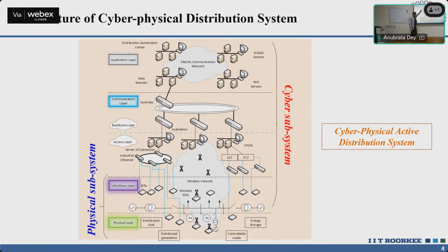And after that, the last layer comes, that is the application layer, where all your systems, let's say SCADA, then you have the advanced demand management side systems or energy management systems, all algorithms, or maybe your, let's say, MIS system, right? All those systems work here in this application layer.